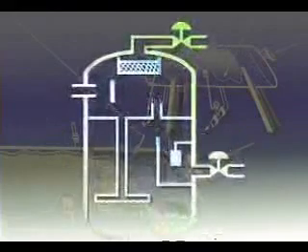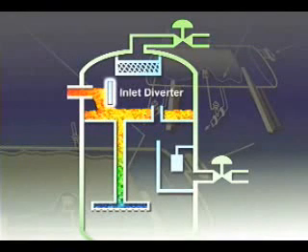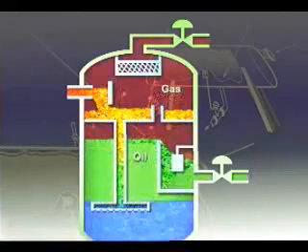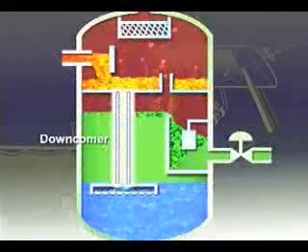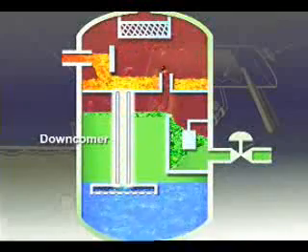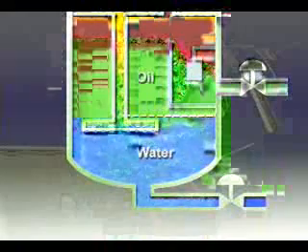In a vertical three-phase separator, flow enters the vessel through the side. As in the horizontal separator, the inlet diverter separates the bulk of the gas. A downcomer is used to transmit the liquid through the oil-gas interface to keep from disturbing the oil skimming action. A chimney equalizes gas pressure between the lower section and the gas section. The spreader, or downcomer outlet, is located at the oil-water interface.